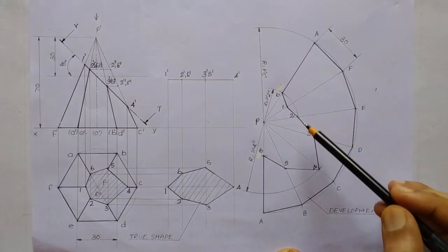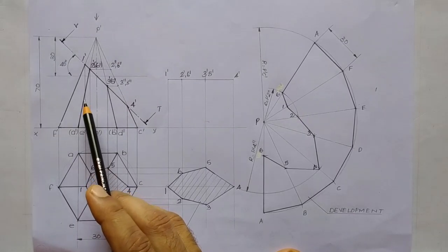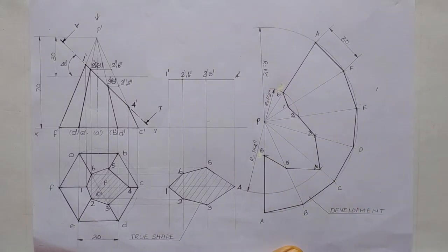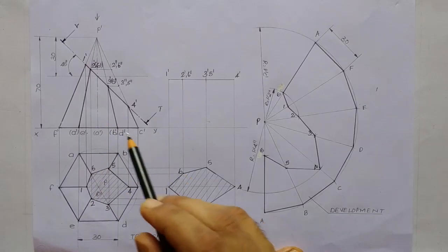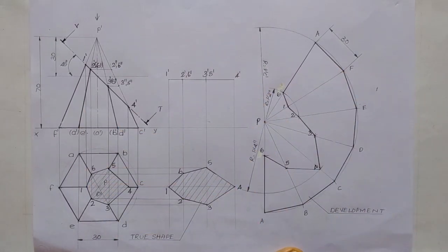So in this case, we have taken these measurements to mark 1, 2, 3, 4, 5, 6 from the front view. So just to indicate that we have followed the correct procedure, we'll be marking some 2 or 3 of the dimensions here. In this problem, we have drawn the front view, sectional top view, true shape and development of the remaining portion of the solid. So usually in questions, you will be asked to draw only a combination of front view, sectional top view and true shape, or else it will be front view, top view and development. All these together usually won't be asked in questions, only a combination. So here I have done it together in order to save time.